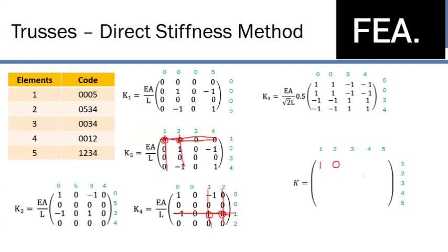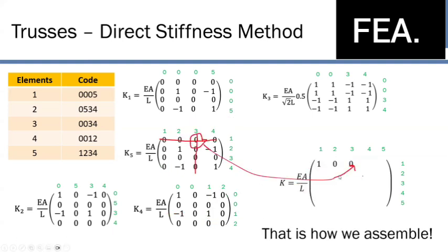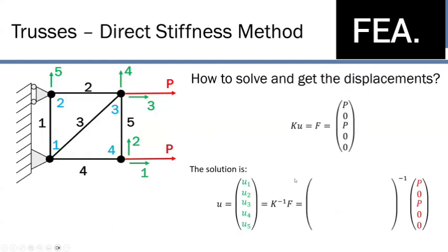The next one, 3, 1, we can go here, 0. The next one, 3, 1, it's just 1, I think. So it's just a 0. So we'll put it right here. But you're just going to basically go all across. And actually, because it is symmetric, you can go through the diagonals. You can go through that top right and then just mirror it. That'll make your work a little bit easier. But once we have this, that's basically all of our work. And once we have this stiffness matrix, we can now get the displacement.